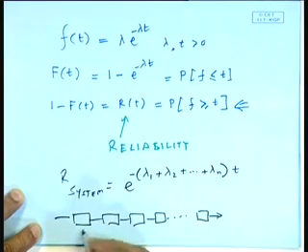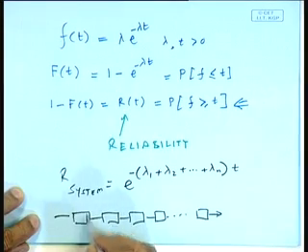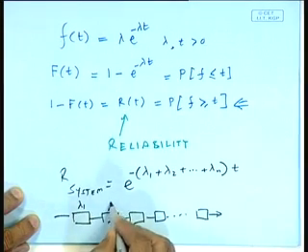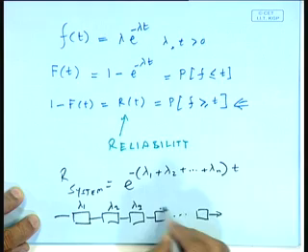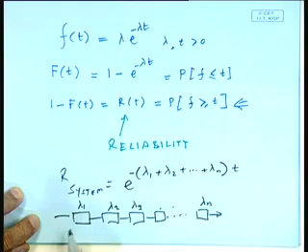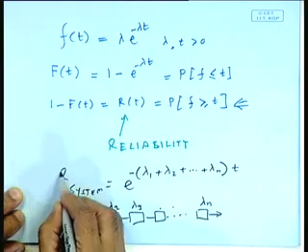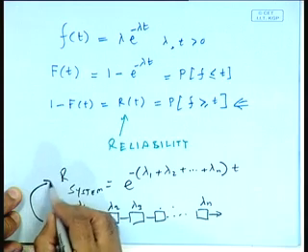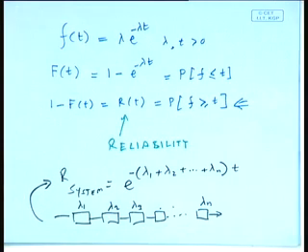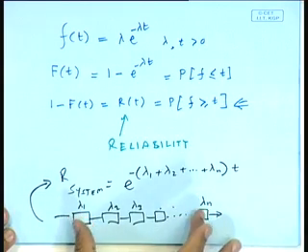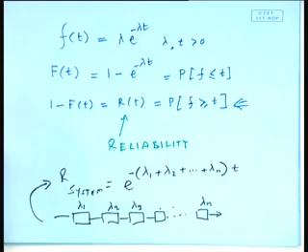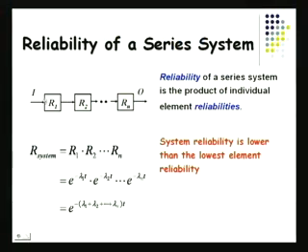And the full system is, this is lambda 1. Failure rate here is lambda 1, lambda 2, lambda 3, and so on, this lambda n. If this is the picture, the reliability of this total system is going to be this. This is a fairly simple, easy to remember formula when every component must survive in order for the system to survive. This total thing is the full system. This is what you see on the screen there. I've got input to output connected, provided all of them are surviving.